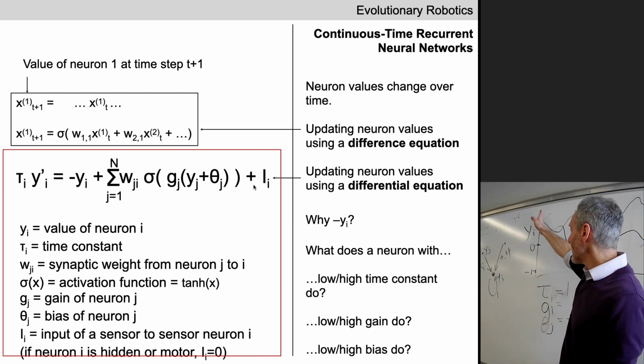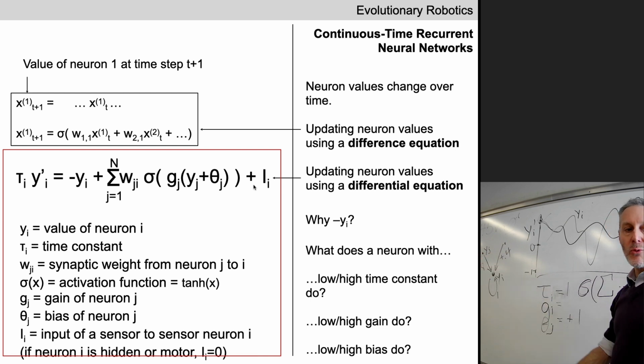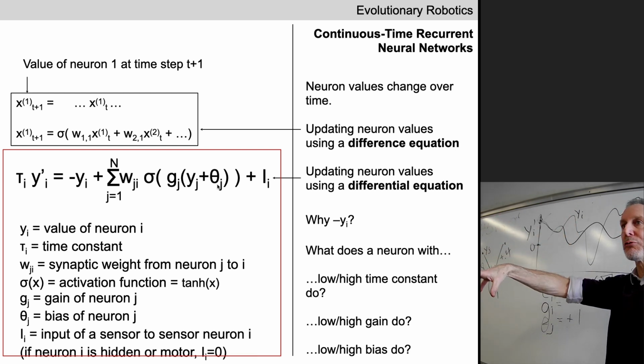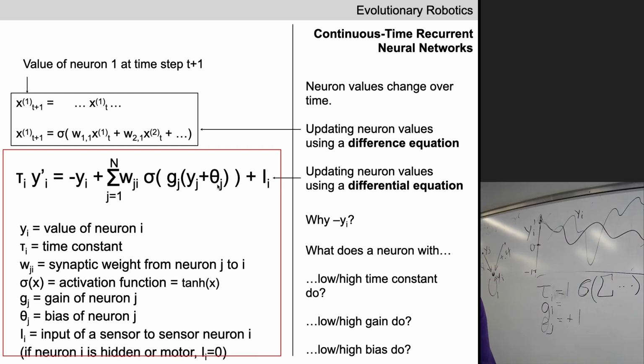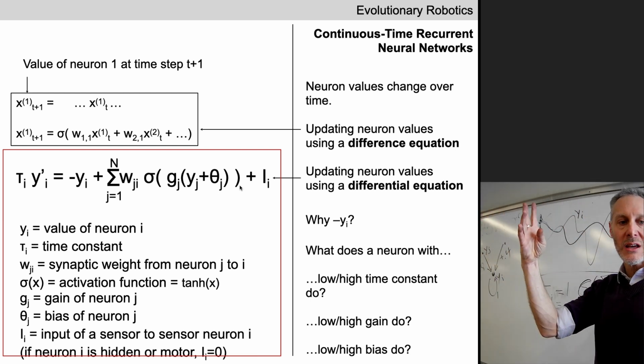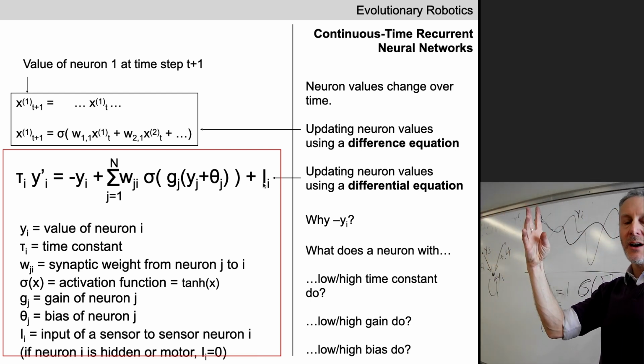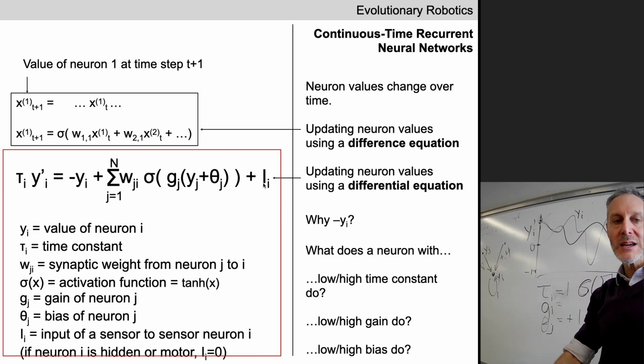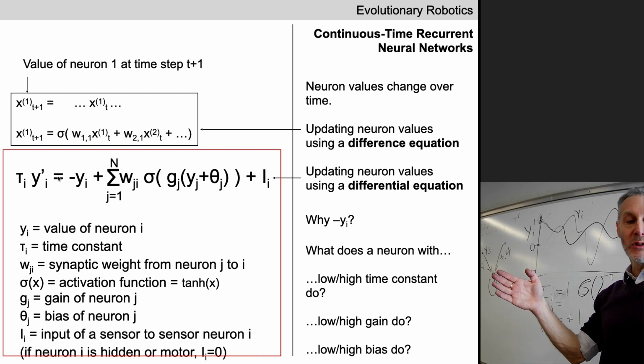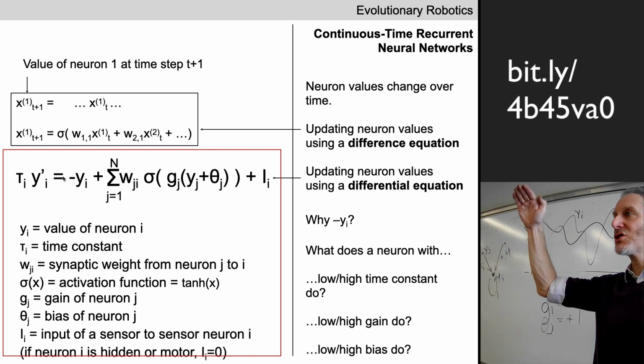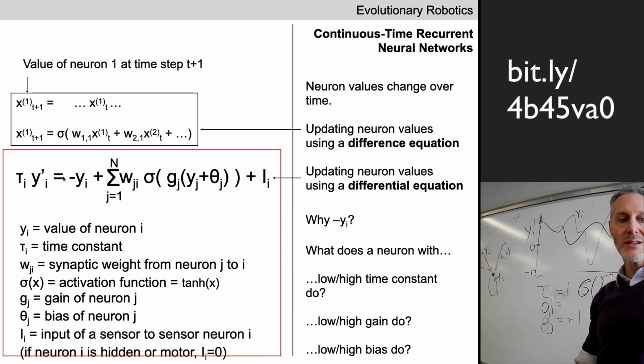Okay, so we drop a CTRNN with random W's, random tau's, random g's, random thetas. We drop this into a 4-legged robot, and the 4-legged robot starts with all 4 feet on the ground. So 4 of the ODEs receive values of 1. The other 15 receive zeros at this term. We're trying to compute the value at the right-hand side of this equation for all 19 ODEs.